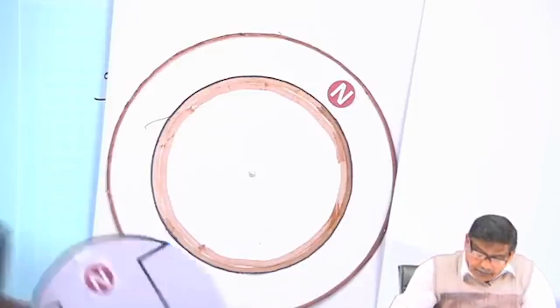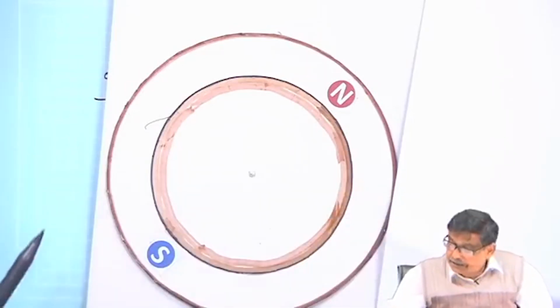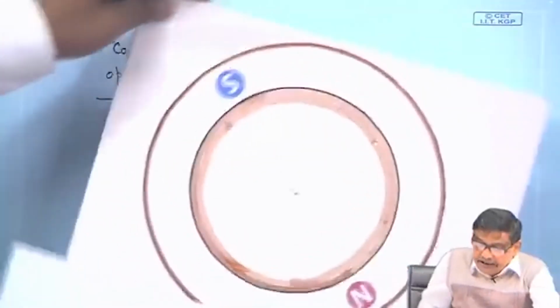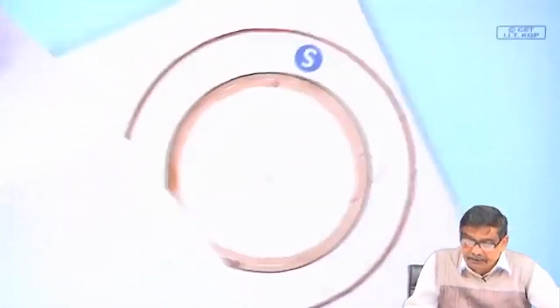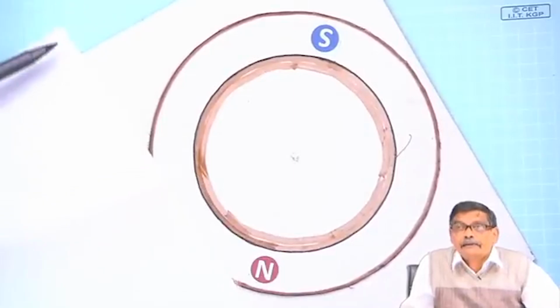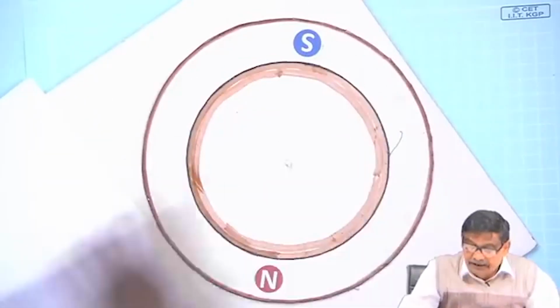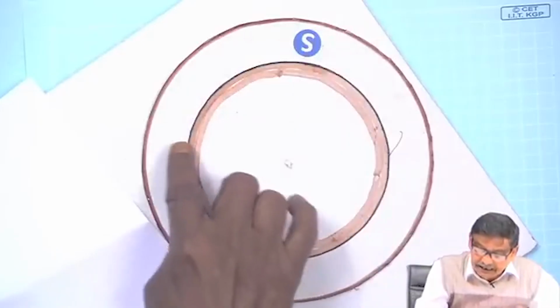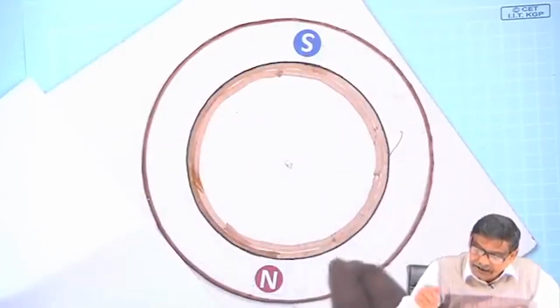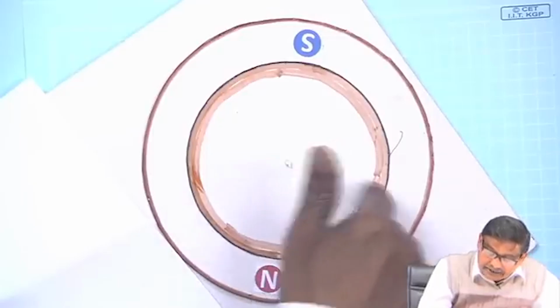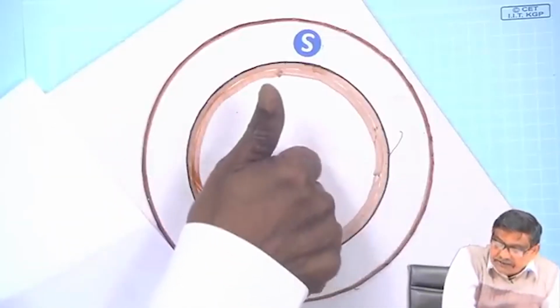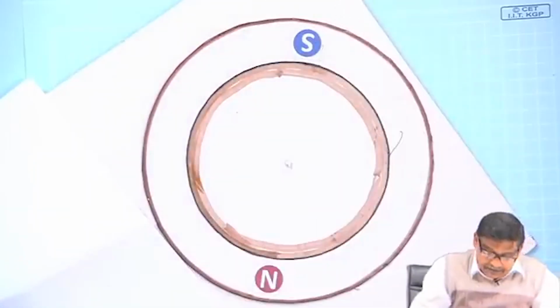Now, similarly, forget about this projected pole business, I will put it like this, the way I have drawn. I have drawn the stator like this. Here is a slot, here is a slot, I am pushing current this side cross, this side dot, so that lines of force will be like this.